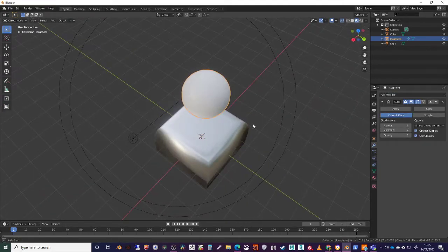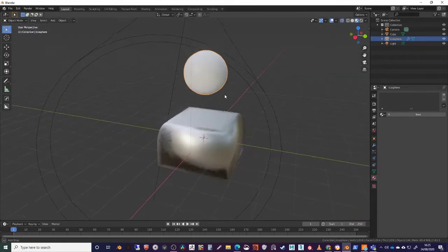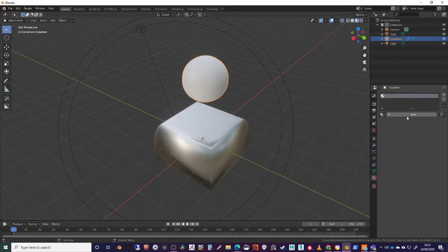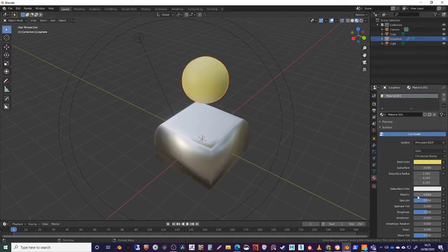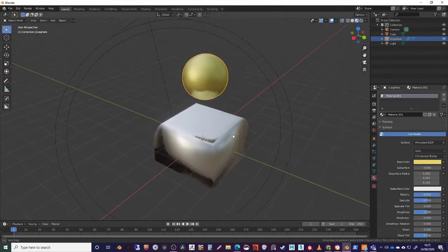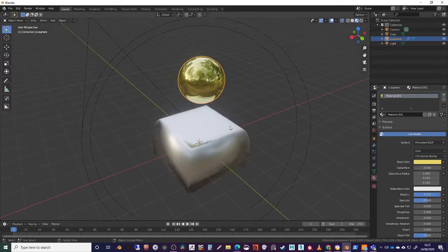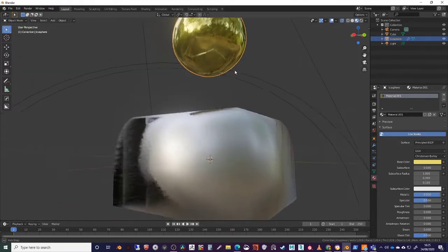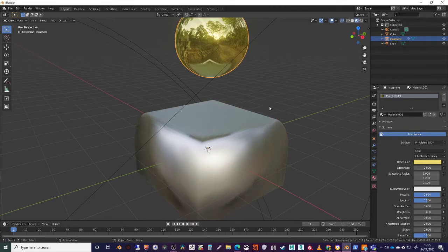These two, if I go in here, add a modifier, we'll just add a subdivision surface modifier and turn that up in the viewport. If we went to the shader, you can see there's nothing attached to this shader. It's not got the same material, so we just need to click a new material. And then this material might be a different colour, and also probably has a bit of metallic in there as well. You can see that the material is obviously with the roughness. If I turn that down, you can see we get this really nice shiny real-time reflections going on. And that's the EV renderer. It's pretty good.